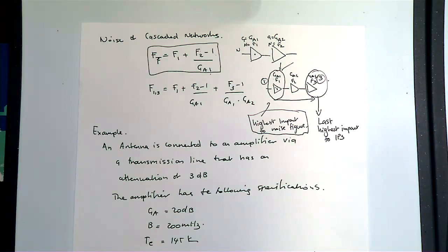If you're trying to design a highly sensitive receiver, what are the key takeaway points that this formula is indicating that you need to do? The first amplifier should have low noise, and should have as high a gain as possible, right? Because why is that? Yes, you're absolutely right. Why?